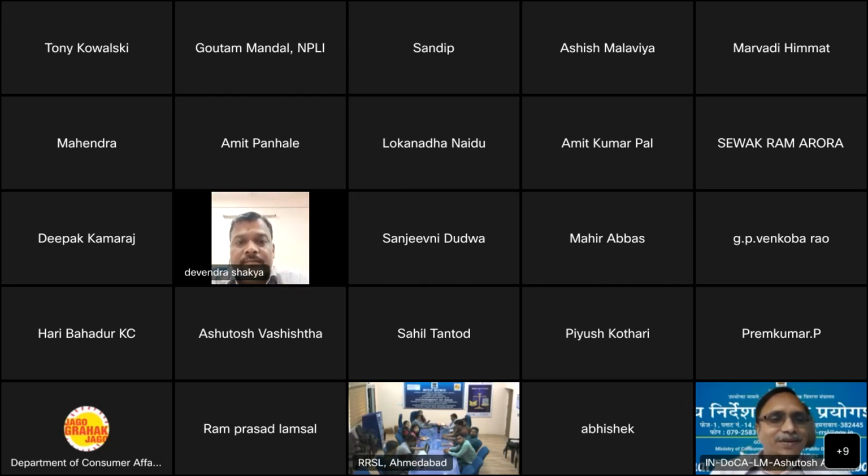Yes. But whether you are also thinking to make it commercialized or something, you are also working on it? Well, NPL has the older model, and we now have a newer vacuum mass comparator, which can compare up to 8 silicon spheres, or silicon spheres and density references for air buoyancy, or just artifacts, or your 1 kilogram national standard. So vacuum comparators are available from Sartorius.